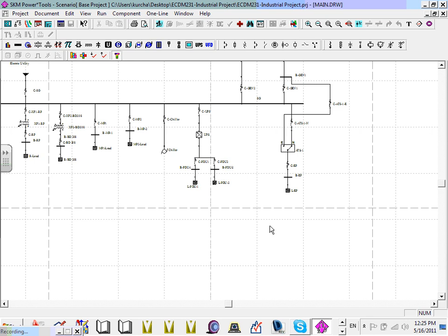So we built the model, we ran the analysis, and we got 0. Like everything in any software, garbage in, garbage out. So if the information that you guys put in the system is not the right information, you will get results, but it would not be the right results. So what I expect you guys as we go through this week is to go back and just adjust the sizes. Everything should stay the same. The infrastructure is the same. The cable sizes will be different and the load size will be different. Other than that, you are 80% done with this part of the project, basically.